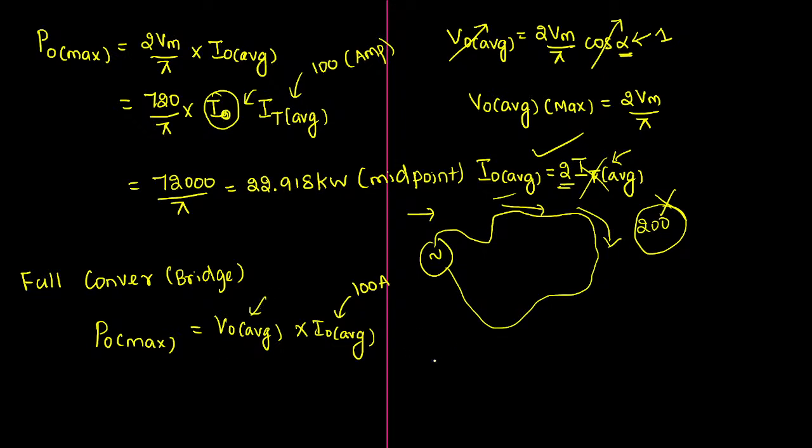How will you do that? Sir, I know, just now I found the peak inverse voltage. If I multiply the peak inverse voltage by the safety factor, that will give you what? Forward peak voltage. Yes, sir. Forward peak voltage is already given as 1800. Peak inverse voltage of the bridge rectifier is only Vm. Safety factor is given as 2.5. So if I divide 1800 by 2.5, I will come up with 720. Undoubtedly, this gives you the value 720.